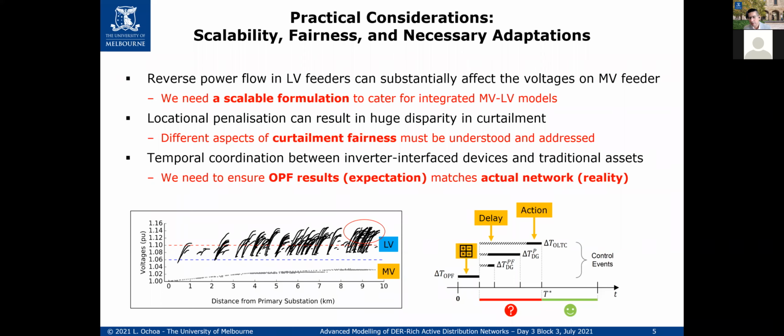Capacitor bank normally will be just checking whatever is the power factor or the voltage, again, at the connection point of the capacitor bank, and then will make decisions. It can be time-based, whatever, but again, it's local. So when we talk about OPF, sometimes we assume that we can control everything. The reality is that sometimes we could, sometimes we cannot. So how do we actually consider all these elements that have a local control?